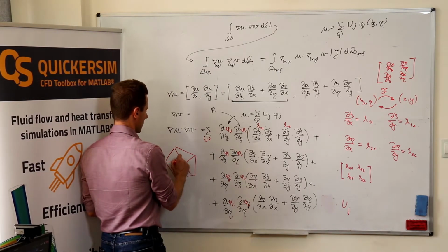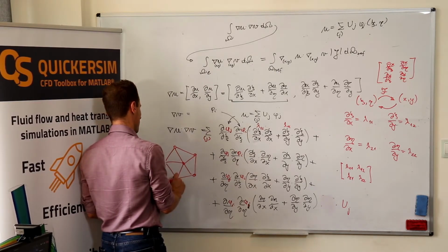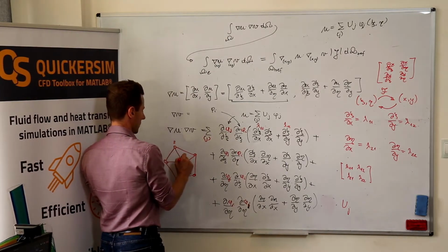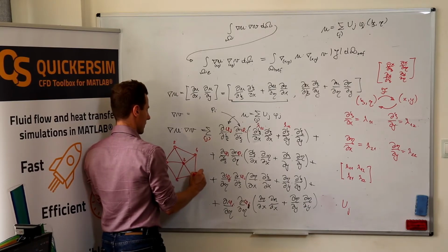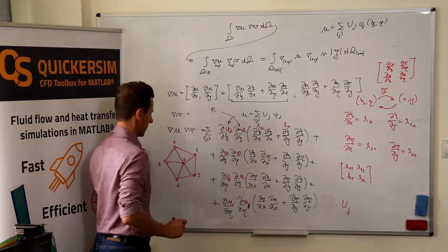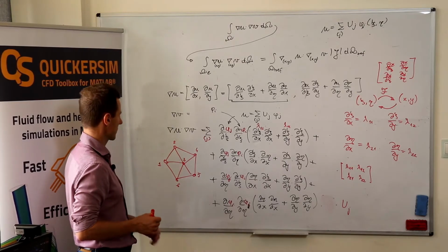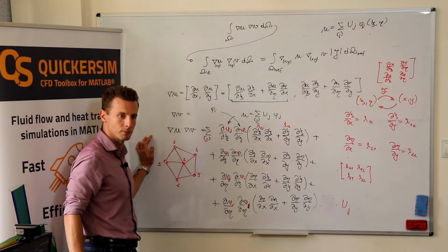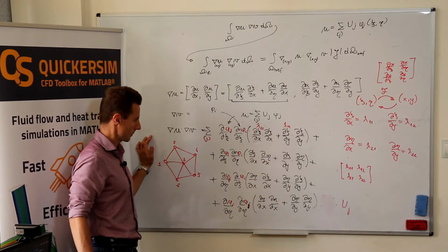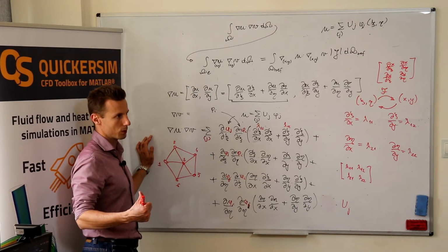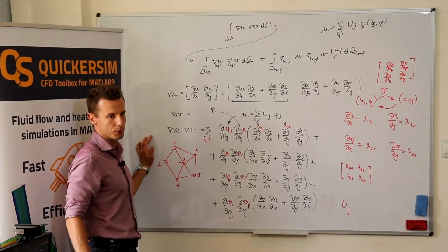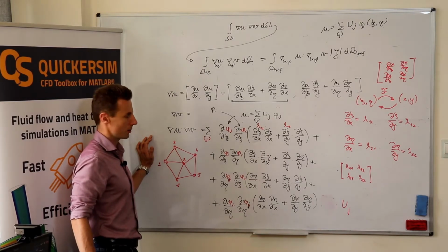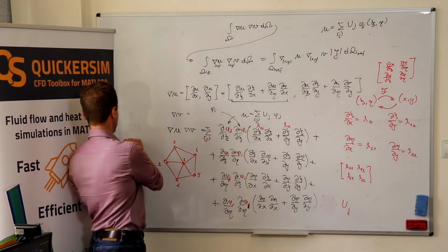If you want to assemble the global matrix, what's the procedure? Do you remember from our 1D example? How would you assemble the global matrix for such a mesh? Nodes coordinates first. But what kind of first loop do you use? What do you loop over? Elements. Yeah, exactly. So you would loop over elements.